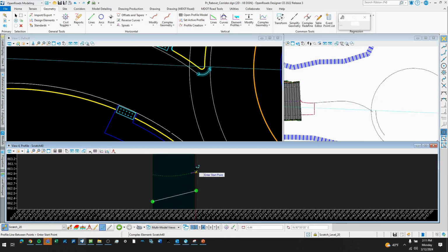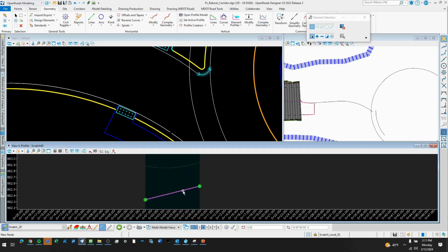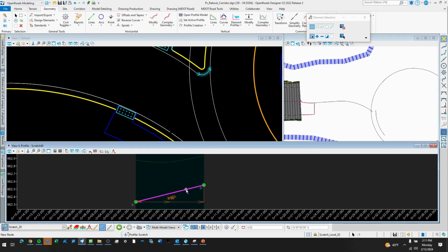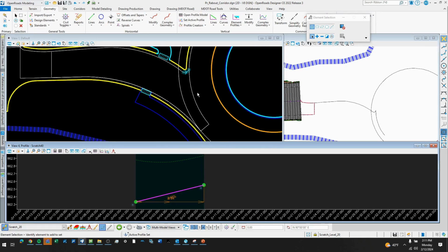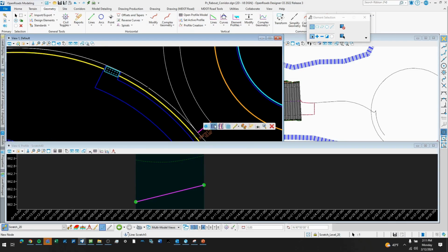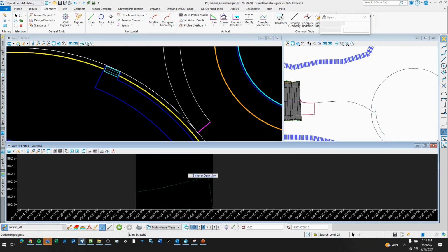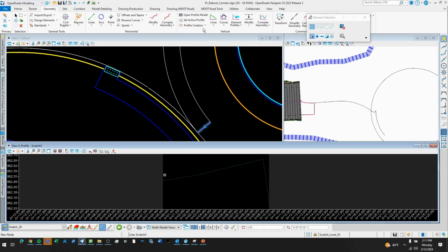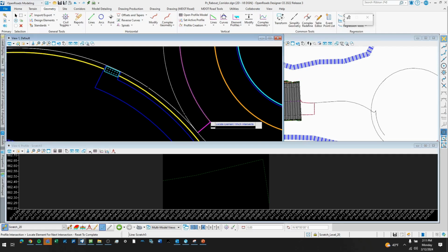Doesn't look crazy sharp. 2.5 is pretty high, but it's not going around a curve, and anything over 3 I might be a little bit worried and may rethink that, but it's such a small distance. And then really from here we can get this edge line and do the same thing. It should come out to be exactly 1.5%.